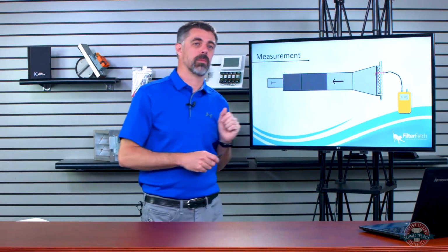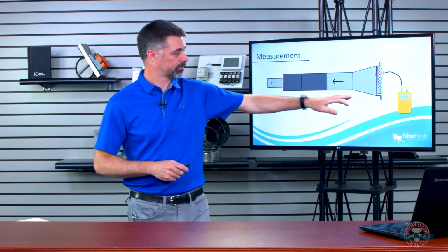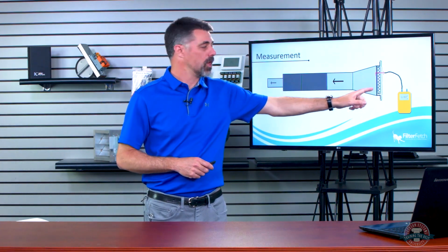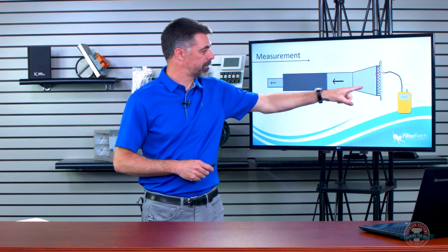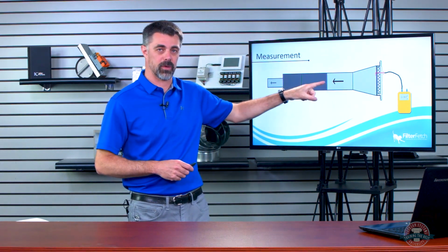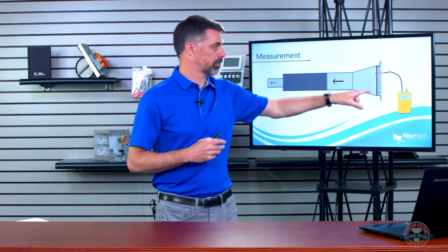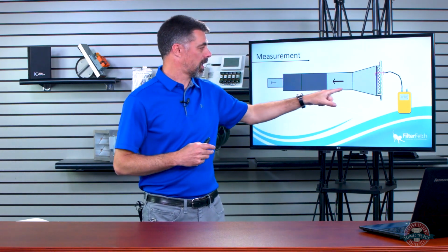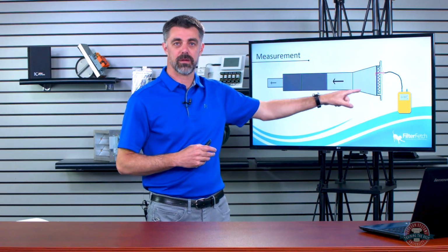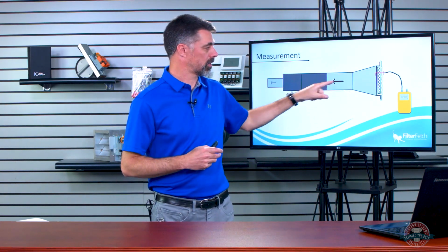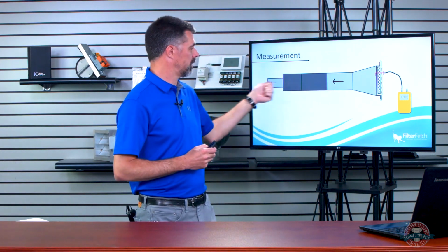One key thing to note on any system using a filter grill like this: you need to have everything behind that filter sealed all the way back to the equipment. Because this whole duct in here is under a negative pressure, meaning it's below atmospheric pressure. So if you bring air in here and you filter this really well right here, but you have a lot of leakage in that duct back here, you're going to suck dirt into that duct. It's going to get the equipment dirty and blow a bunch more dirt back out into the house.